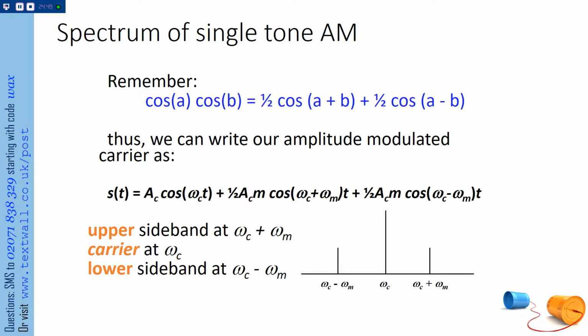If you remember, from week 5 or 6 last semester, properties of the Fourier transform, there was something called the frequency shift property. And I called it the modulation property. And you said, why is it called modulation property? And I said, I'll answer that next semester. So the modulation property is a frequency shift property. When you multiply something by a cosine, the spectrum is shifted up by the frequency of that cosine. That's why it's called the frequency shift property. But frequency shifting is what modulation is all about. Modulation is a frequency shift.